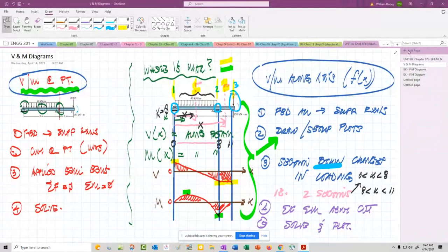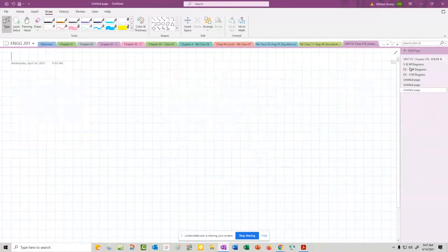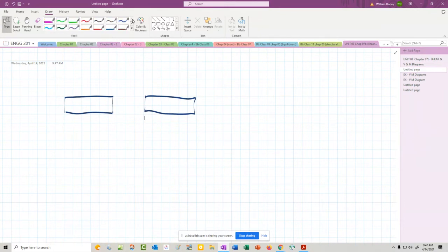All right, so continuing on with this, we're going to use the same sign convention. Let me just do that again. When we shear that beam, we're going to have the same design convention, meaning what's plus, minus, and all that. Our shear is always going to be down on this side, up on that side. Again, we're looking for a clockwise rotation.